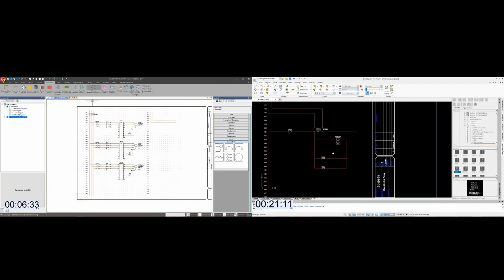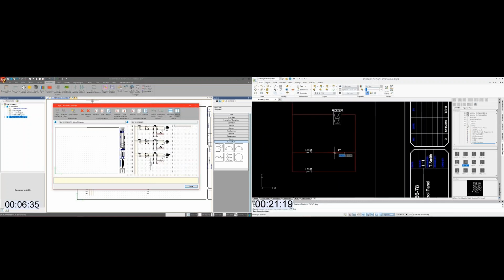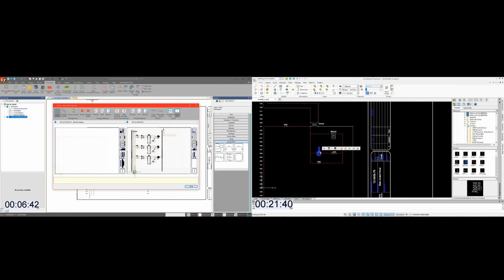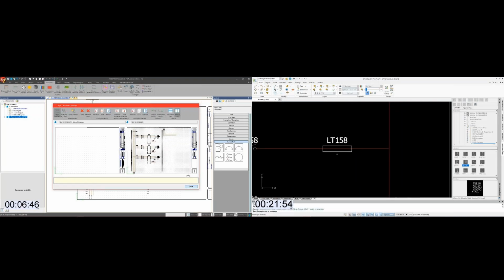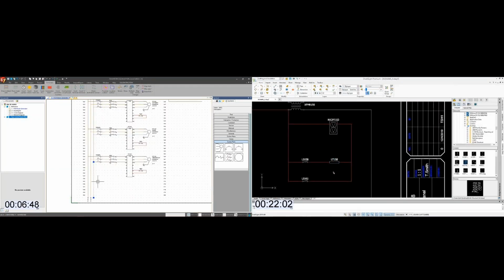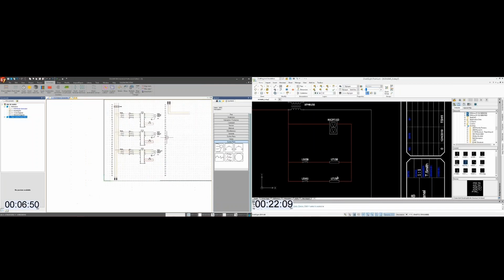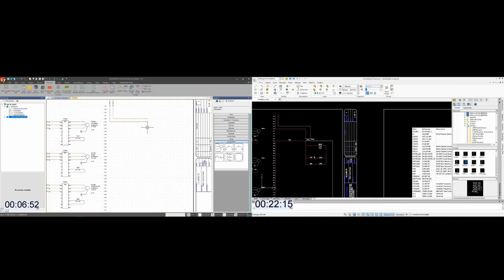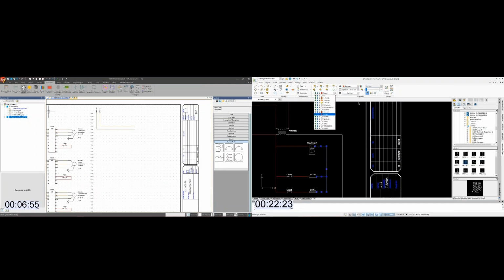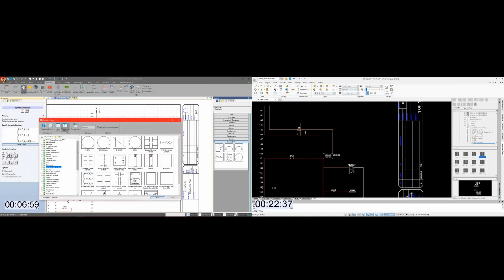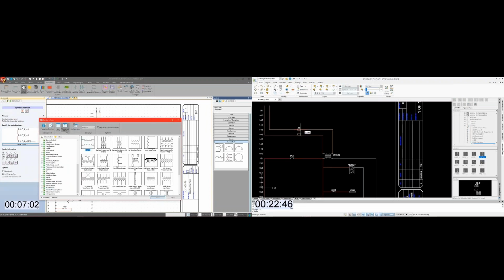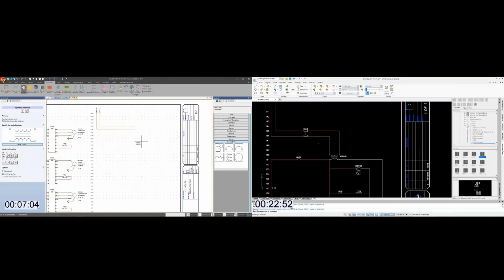All right, so checking in here again, let's stay in SolidWorks Electrical, because here's a nice feature. What I'm doing is putting in intelligent source and destination arrows. So I'm saying this wire starts here and continues here, driving the intelligence of those wire numbers behind that. Once I make that association, all the wire information is intelligently fed through those connected wires through source and destination. Super easy to manage, compared to the manual effort it takes on the CAD side, which can be complex.